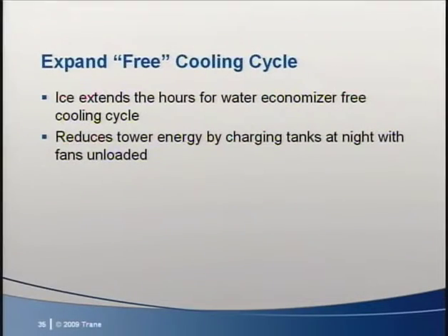While we design the system to handle the design day, there will be many cooler days when ice can do even more. Water economizing cycles often can't meet the load with just the economizer. If the ice were in series and downstream of the economizer, we get the benefits of the chiller working against a cooler condition at night. Cold tower water is not free, and ice provides another level of flexibility for minimizing system energy.